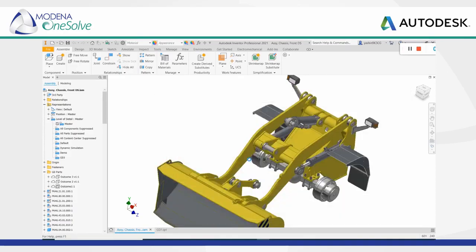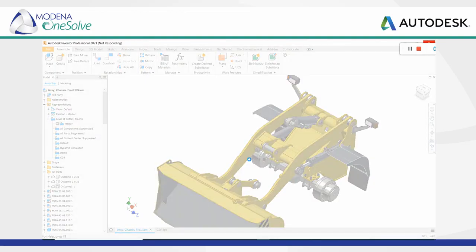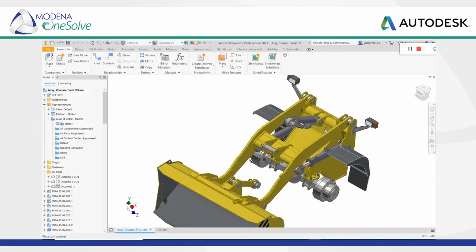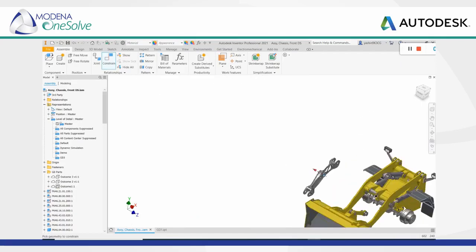So what I can do from here is bring that component into Inventor, place and constrain it. It will take a couple of seconds to load, of course, because it has to download some information from the cloud and bring it back into Inventor. So what it's doing over here is just converting it to the latest version, and a readable format that can be used inside of Inventor. And as you can see, I can then go place that component, and of course I could then constrain it in place.